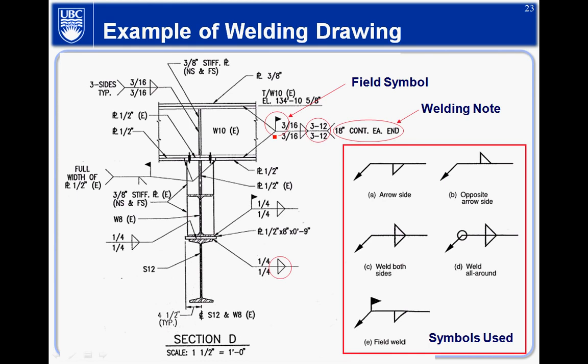Anyway, what I want you to remember, or to understand, is a couple of important things. Remember this one represents the fillet weld, and remember what this down here means: the arrow side. This is the other side. If there's a number here, that represents the leg size, because that's a very important value. You're going to need that. So those are basically the essentials I need you to understand.